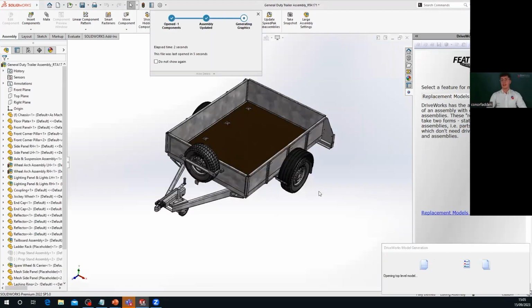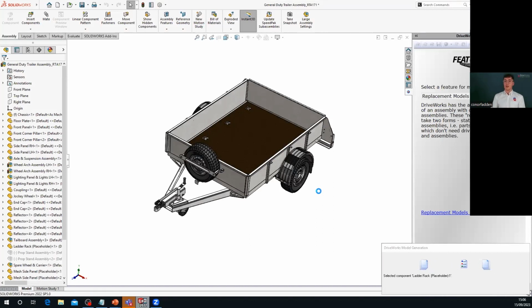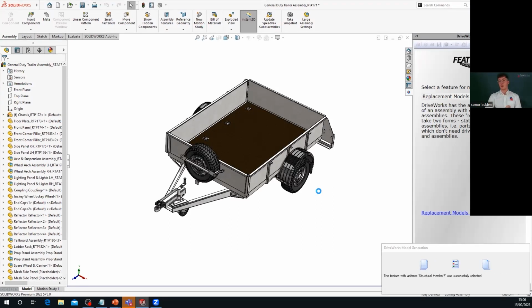So now, once again, this will go through, take a copy, as I've already said, of our actual master model files and put them into our specification location over here, amend all of our changes. And this time we're hoping and wanting to make sure that our actual wheel, our spare wheel, isn't included inside of our final assembly. Now, this will take approximately, I'd say around 5 minutes or so, just to configure, as you saw previously. So we'll just go through this whole process again.